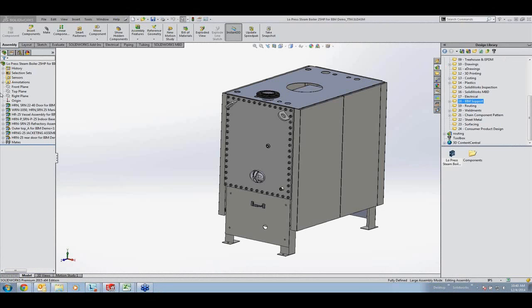Of course, I can change my fastening options here. I can change chord tolerance, segment length, etc. And when I flatten this, you'll see that it gives an accurate flat pattern with bend angles, or bend lines, excuse me. All right, let's go back to the completed model here, because we need to make some changes to it.